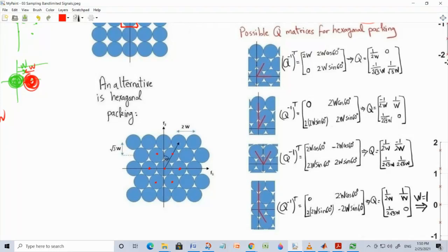And again, in principle you are able to have a low pass filter that will extract the original CTFT. You don't have overlap, so it is perfect reconstruction. Of course, there is nothing perfect in reality, because you never just do sampling. You do sampling and quantization, and there are always practical issues related to sampling and quantization. But you can reduce those bad effects as you wish.